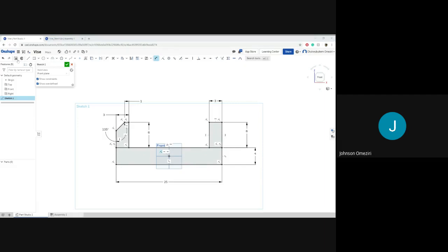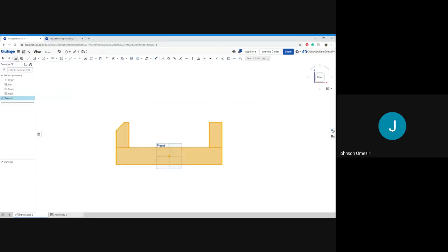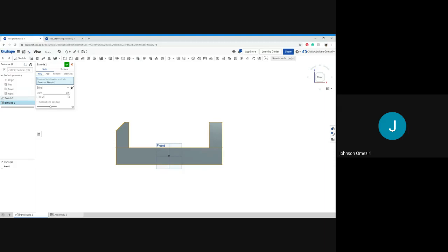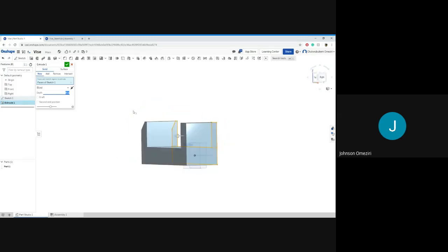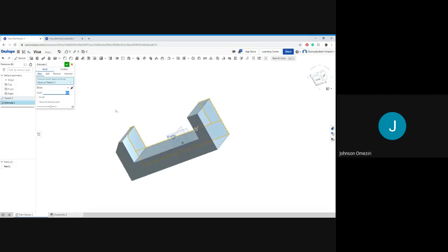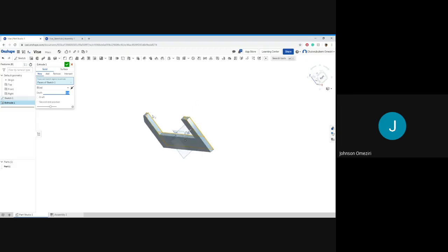Then you can just click on extrude here, the extrude boss or base, or press Shift E. So click on that. In this field here, we set the depth to 8 inches. We set 8 and enter. Okay. So I can use my right mouse button to rotate to see what I just did. So that's what I just did. Setting it to 8. So let's just put 1. You see what it changes, it changes the size. So I'm setting it to 8 here. That's how wide I want this.